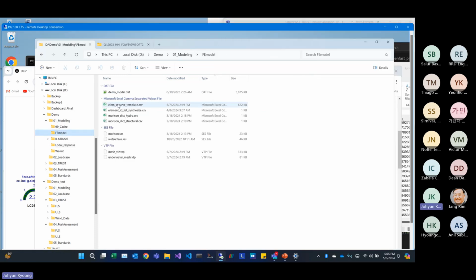Using the structure model, the weighted surface area element file set is extracted, with the corresponding data points mapped to WAMIT. WAMIT calculates the corresponding structure nodal point pressure. Then later, this WAMIT pressure output is mapped to the structure directly at the corresponding element.